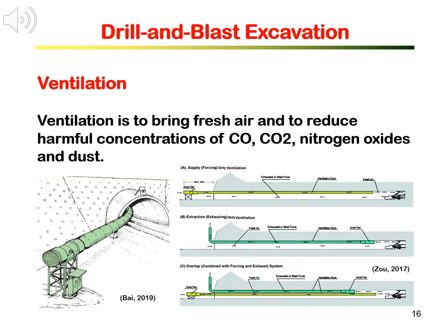After blasting, the next activity is ventilation. Ventilation is to bring fresh air into the excavation space to reduce harmful concentrations of CO, CO2, nitrogen oxides, and the dust produced by blasting.